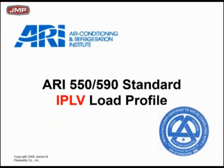Here's a reference to ARI 550, which is the original IPLV load profile. For those of you who are not familiar with this, just to put it real simple, it was a standard that all chiller manufacturers through ARI agreed to: take a standard ARI-approved load profile, look at kW on a chiller, and rate their chillers.